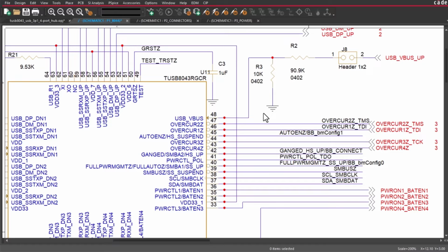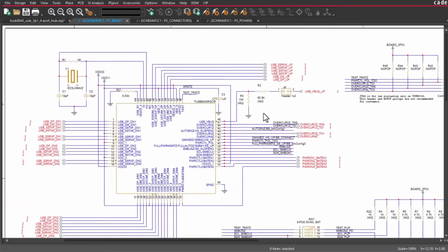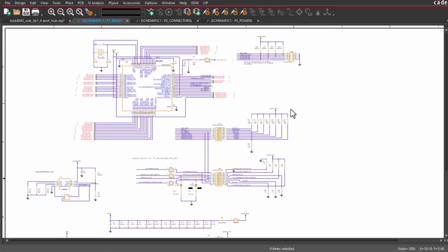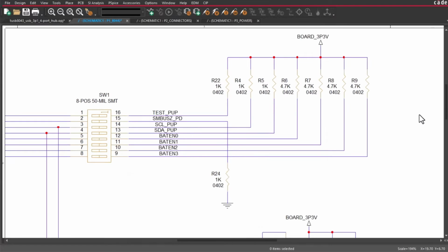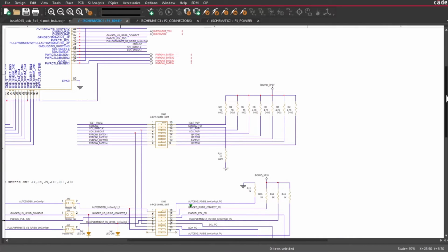And the higher the speed of the design, the more powerful you want the software tools to be, because they account for more things, they make your life easier, and can handle the little nuances and errors easy to miss by having design rule checks, by having signal integrity analysis even in the schematic phase. So things that really give you a safety net when you're designing boards that can get pretty expensive.